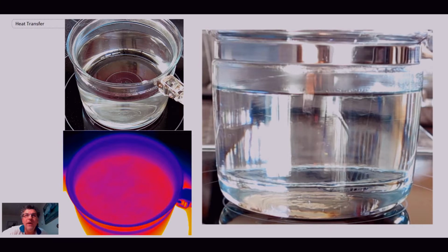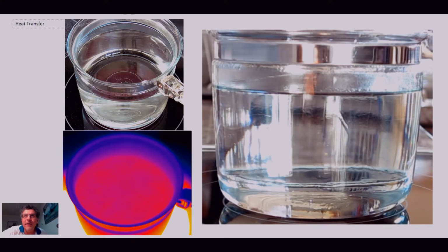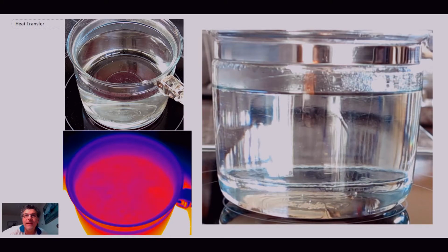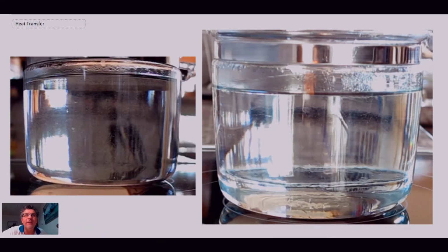But as we move on, noise is going to start. So we start getting noise coming in here. And what that noise is caused by are bubbles forming at nucleation sites on the surface, and then they collapse. And it's that collapsing process that we hear. And now we're going to go to high-speed video.